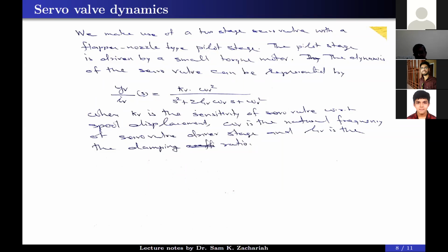Here it uses the principle that the nozzle diameter will be very, very small. So for closing the nozzle by a flapper, we require only a small force, because the area of cross section multiplied by the pressure will be less. There is a concept here. If you are very much interested, I can show the diagrams. Otherwise, it is available in various textbooks. You can just read it if you want. For the knowledge, I can explain in the next class, because without a figure, I cannot explain.